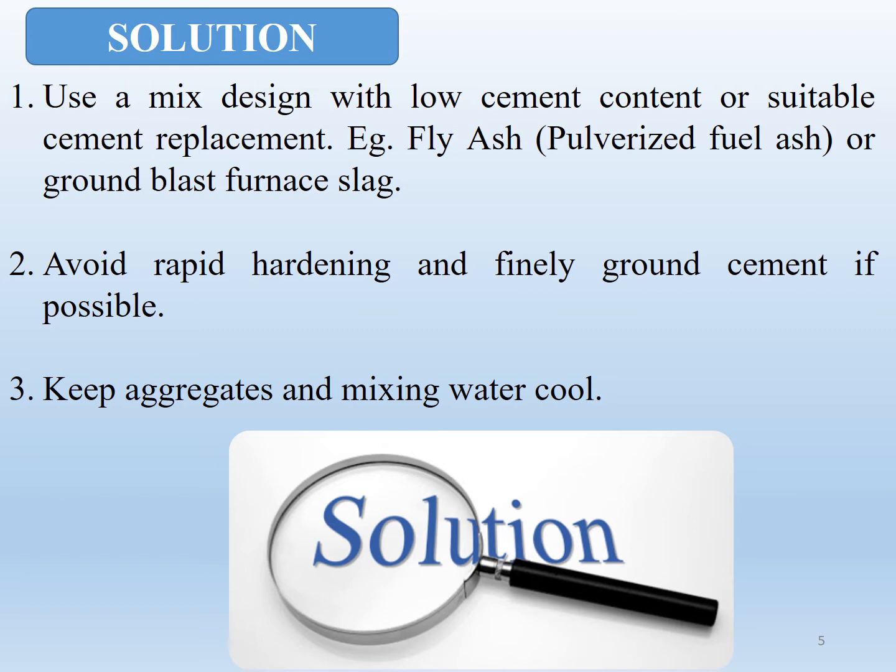The second precaution we can practice: avoid rapid hardening finely ground cement if possible, because rapid hardening cement has a high rate of reaction. The third one is common sense: using chilled water in the concrete and using the coldest aggregate can minimize the temperature difference problem.